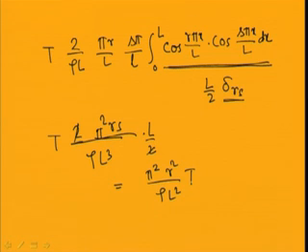As you already know, omega n equals n pi by L into root over t by m. So, omega r will become r pi by L into root over t by rho. I am using rho.